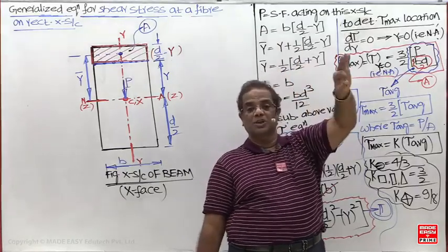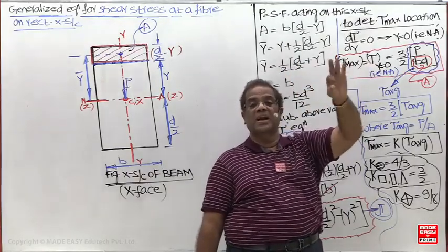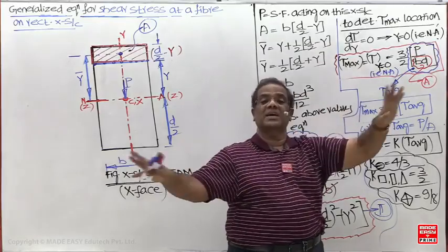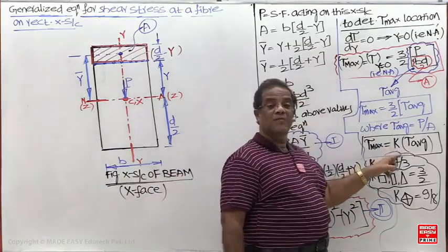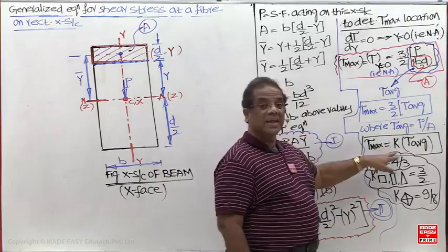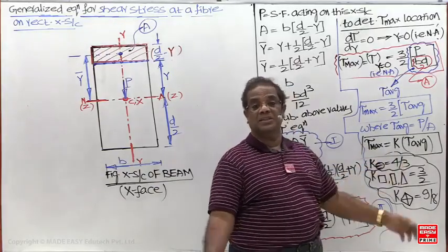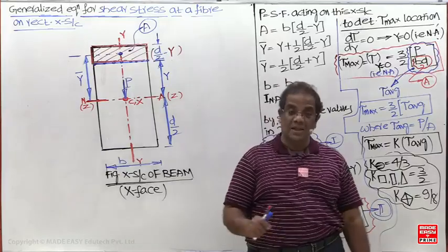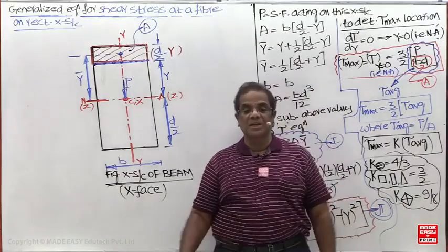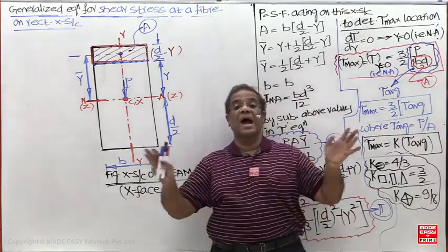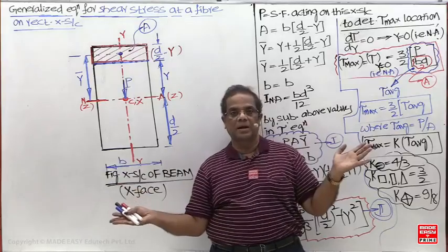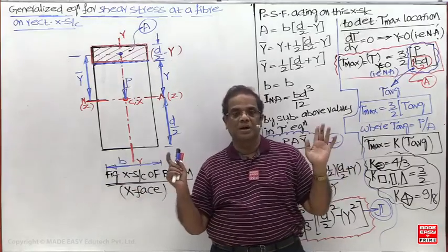In the design of machine components, the design of bolted, welded and riveted joints, in entire machine design, we go for average shear stress. Taking K equal to 1 means I am assuming the maximum shear stress and average shear stress are the same. So in total machine design, we are considering only average shear. This assumption is made. Why am I particularly mentioning this now?